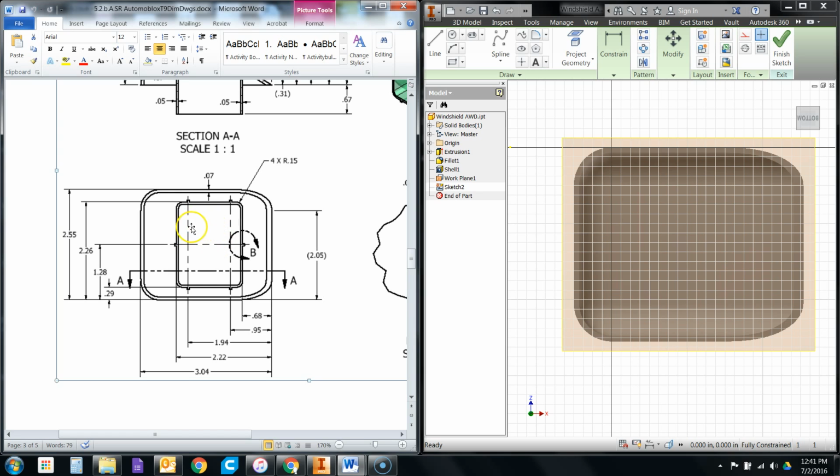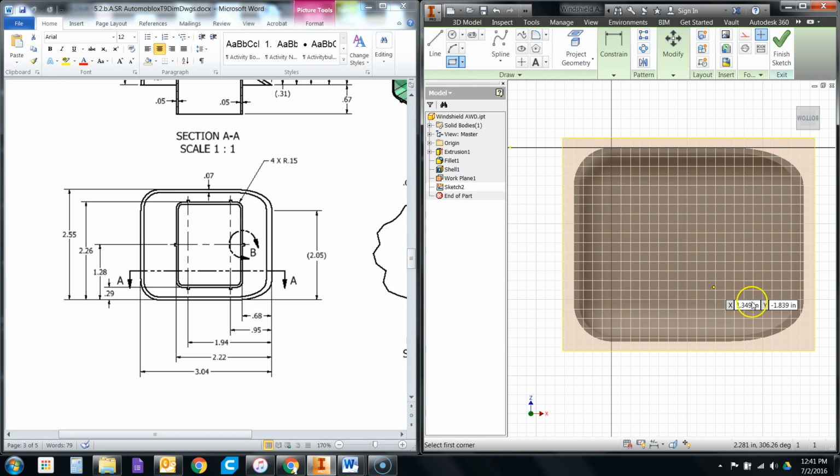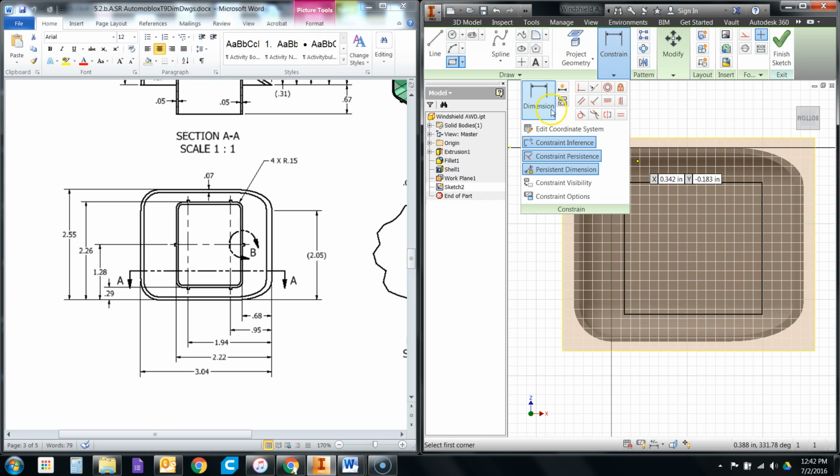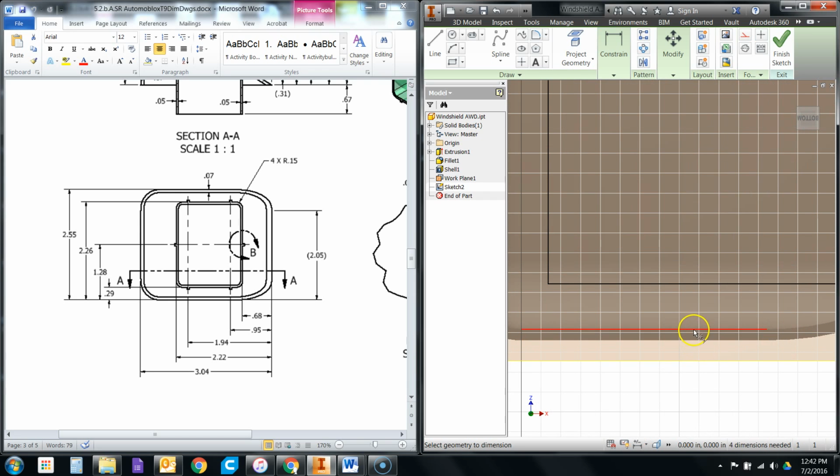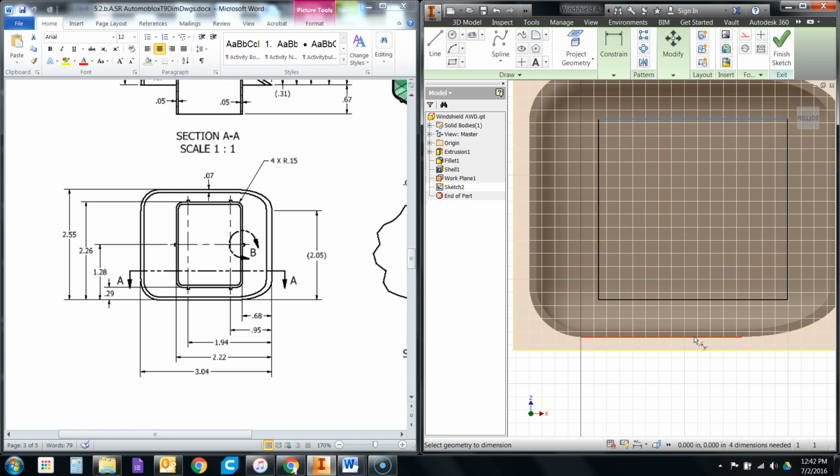And I'm going to do that before I finish this, but I want to show you some different tricks of how I do it. So, starting off with just a 2-point rectangle, trying not to constrain it accidentally to anything, I'll click and drag and pull it out so that it's about this big. Notice that they don't give us the size as much as they give us the location, and they're saying that 2.26 inches is how far it is from the outside edge of this shelled object from before. So I'll constrain this edge with a dimension here all the way down to this outside edge, not the inside. Be careful with that. You want to go to the outside edge.